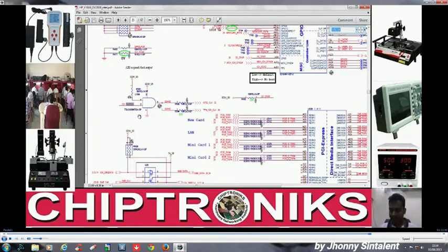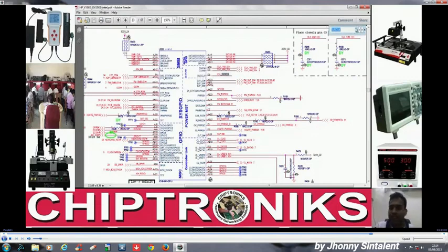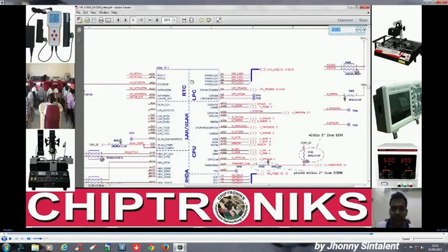Mind it, if we measure the value over here by a frequency meter, not an oscilloscope, it will show 32.768 kHz, and at SUSCLK also it will give you 32.768. What is different is the shape of the waveform.